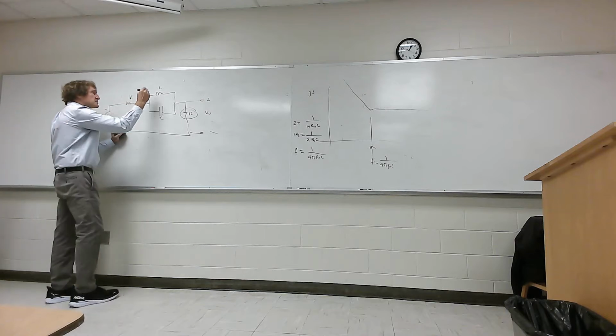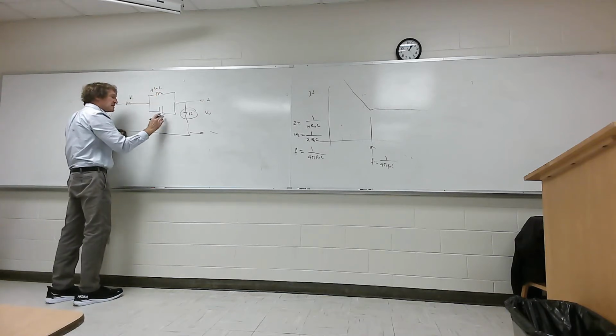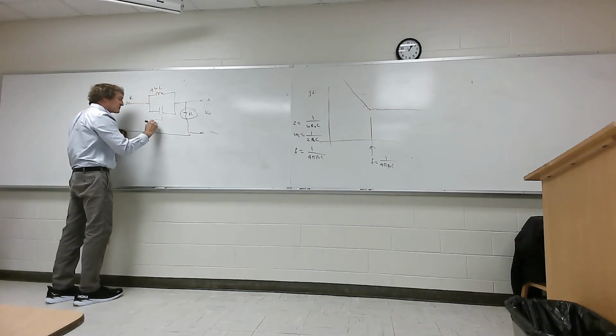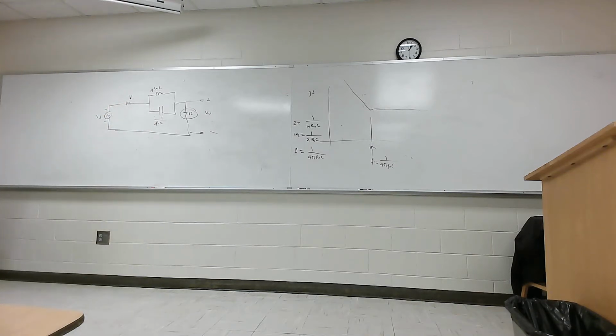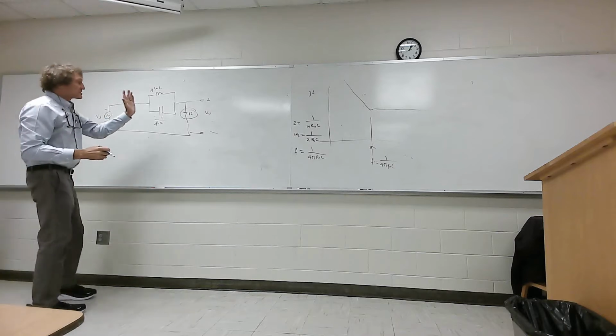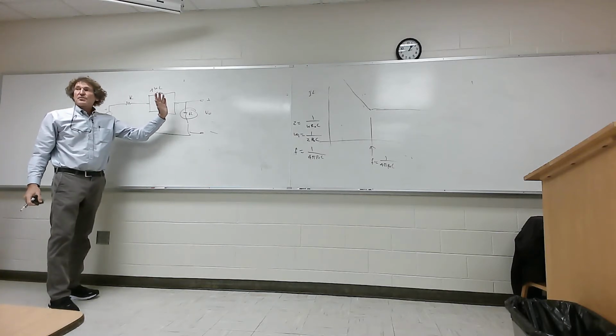Well, the impedance of this is j omega L. The impedance of this is 1 over j omega C, correct? Now, whenever you see elements like that, an LC in parallel, when it's at resonance, it looks like an open circuit. Y'all hear me on that? All right. At resonance, this appears as an open circuit. The further off resonance you get, the more it looks like a short.